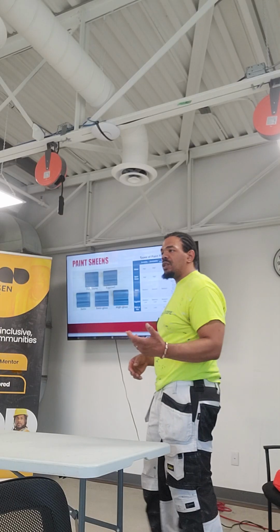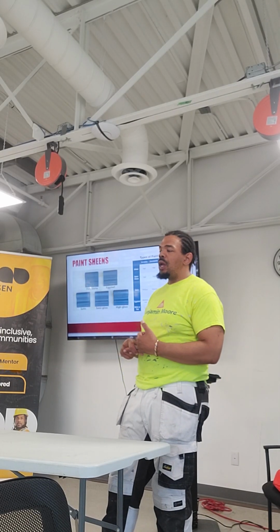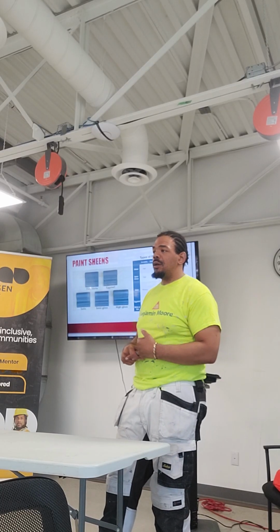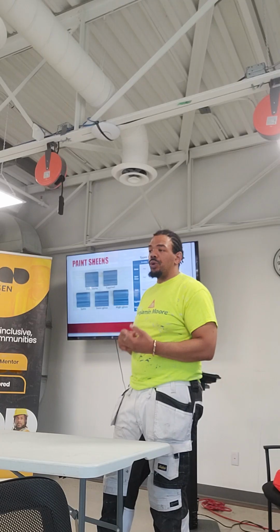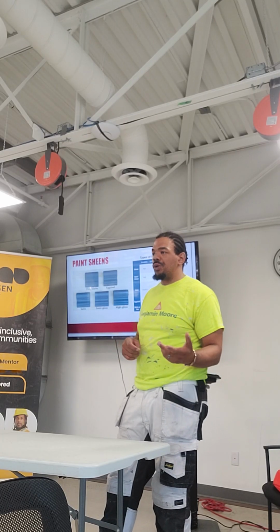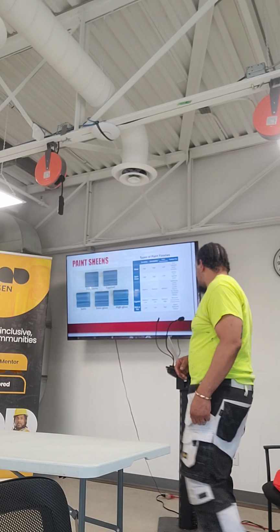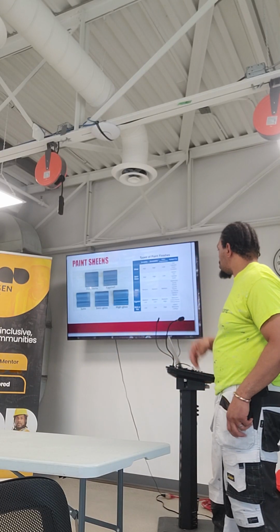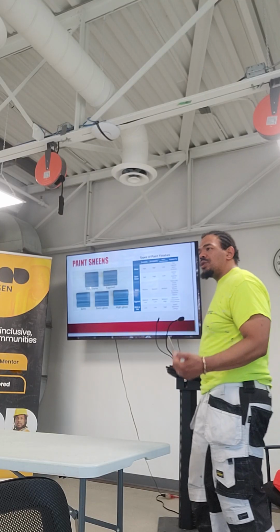So you really won't see semi-gloss much on walls unless you're in a kitchen or a bathroom because they need the water resistance. Okay? You can get a semi-gloss paint and you'll see it mostly on doors and trims. Some accent walls you'll see they use semi-gloss paints on. But that's usually where they primarily serve their best purpose. Satin, you can use anything.